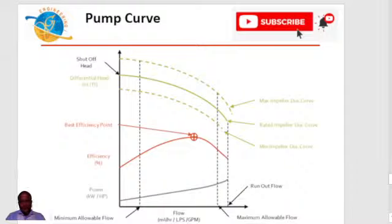You can understand this from the following arbitrary performance curve, like I've explained. The flow is recorded on the horizontal axis, while all other parameters are shown on the vertical axis: parameters like the power, the NPSHR, the shut-off head, and your differential head. As I mentioned, as your flow is increasing, your differential head is decreasing because of the shape of the pump curve.